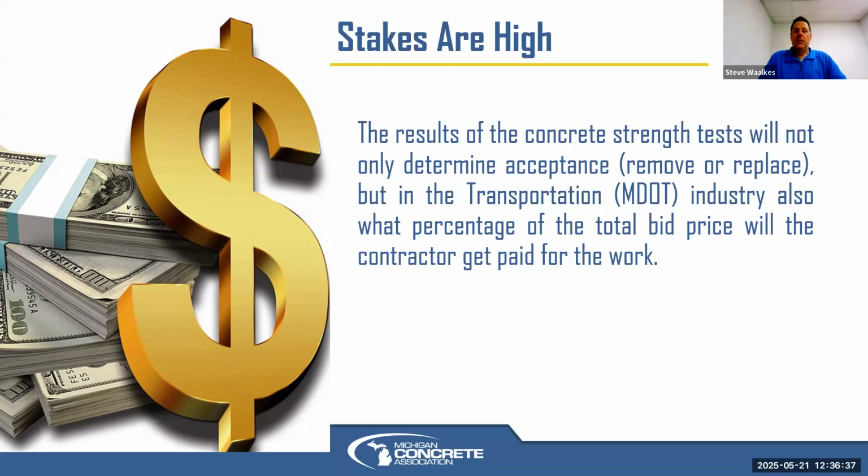And so we are talking with some of our counterparts in other states where their DOTs or others have switched to that. And so we'll see if MDOT is interested in that or not. But a 56-day strength, because some of these cements are a little slower in gaining strength, and there is still some significant strength gain beyond 28 days. So, and there may be pay factors as a result of it, depending on, I think, on MDOT high quantity concrete paving jobs, they typically do a pay factor based on both strength and smoothness. So strength is a portion of that.